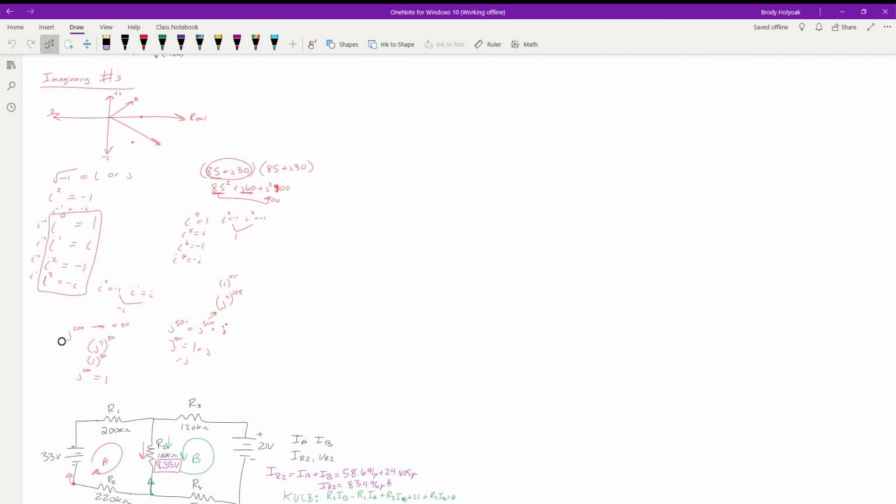The idea behind this is we have real values, we have resistance values. So the way to think about it is this is resistance, and this is resistance that's coming from a capacitor. Okay, they're two separate things. The one with the capacitor, we cannot physically measure. It exists, but we can't measure it. We can measure the effects of it, but not that value itself. And so we have to keep those guys separate. We cannot add them together. We can add them together with Pythagorean's theorem and trig, but we can't do it just normally.